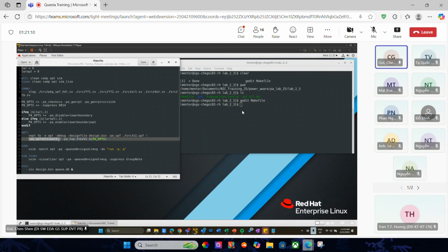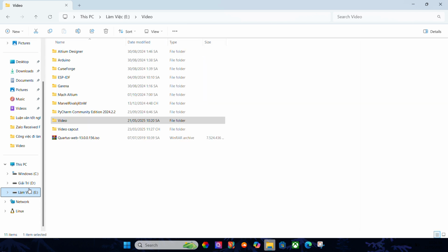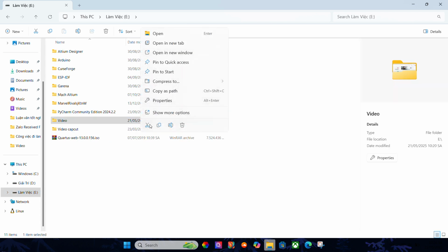Then we can also choose to specify what version of UPF we are using. If we don't specify it, that's okay as well. And then here we specify which PA top is the instance of PA top. So d1 is our instance top at PA. So we also have additional options on PA. So we switch on -check equals s. So static checks is switched on. And then we also have generated report and gen report of source and sink information.